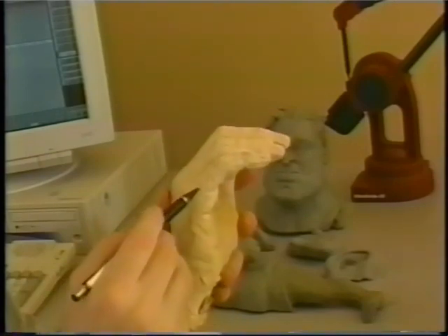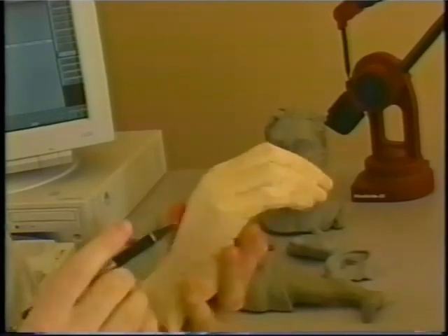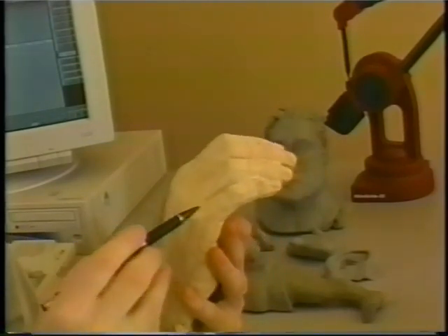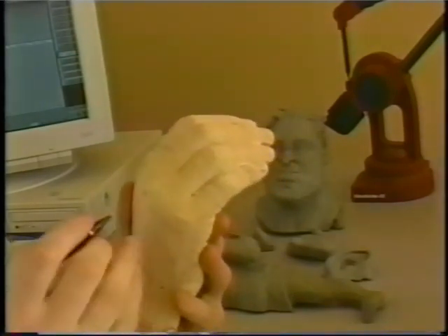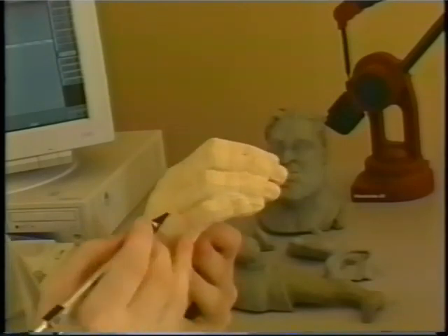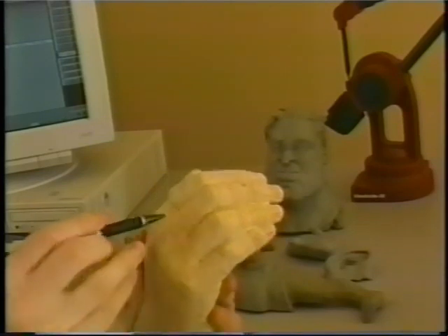You continue on, and you make basically a hand with more lines than it needs to have, with more curves, and so those curves look like they're continuing. And you grab those edge points. If these are B-splines, it's much easier because you have those edge points. You can magnet onto there, and it actually looks really nice. It looks like it's a continuous surface.